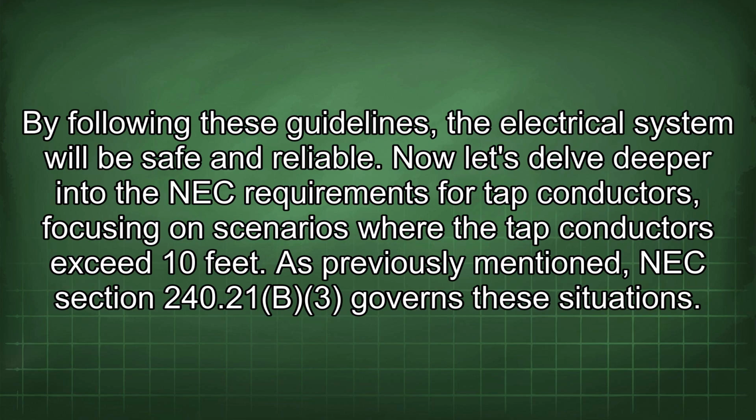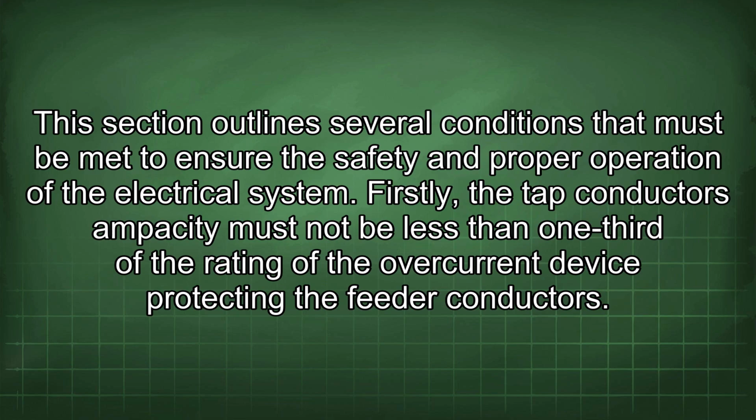Now let's delve deeper into the NEC requirements for tap conductors, focusing on scenarios where the tap conductors exceed 10 feet. As previously mentioned, NEC Section 240.21(B)(3) governs these situations. This section outlines several conditions that must be met to ensure the safety and proper operation of the electrical system. Firstly, the tap conductor's ampacity must not be less than 1/3 of the rating of the overcurrent device protecting the feeder conductors.